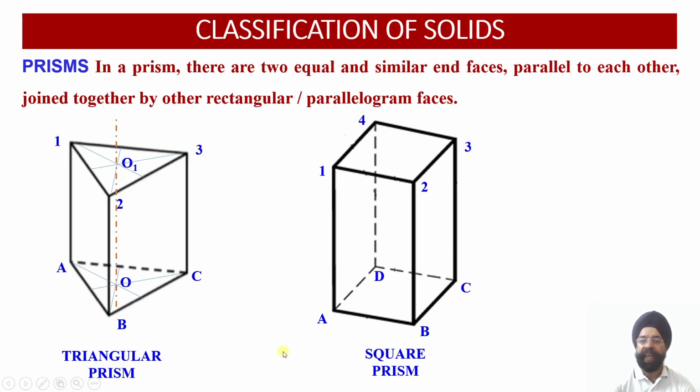Now whenever you make any construction of the oblique solid, one thing is very clear. A, B, C, D have to join under all circumstances. 1, 2, 3, 4 have to join under all circumstances. Similarly, A1 must be joined, B2 vertical edge must be joined, C3 vertical edge must be joined, and D4, that is the vertical longer edge, again must be joined. So if we carry out the numbering in this way, it is very easy to remember which points and which edges are to be joined over there.